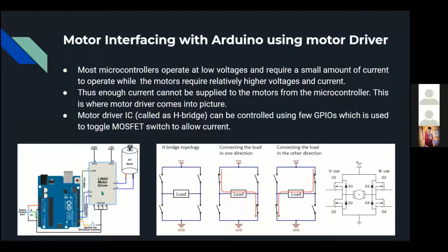One is that it is capable of driving only 2 motors, and one more major concern is that it can't supply more than 1.5 amps. Likewise, if one of your motors is consuming around 1 amp, and another motor has a limitation of only 500 milliamps, you can't boost it due to its internal circuitry's limitations. You can't increase your current consumption.